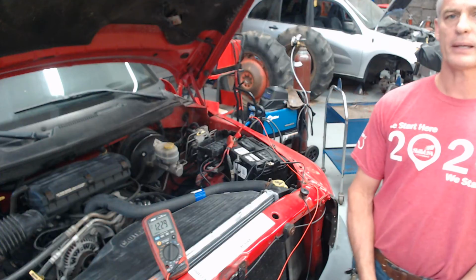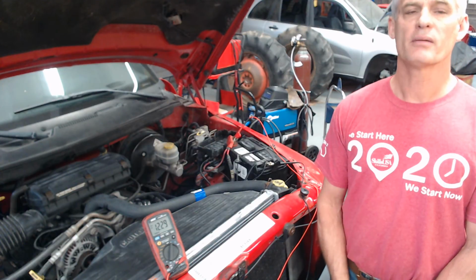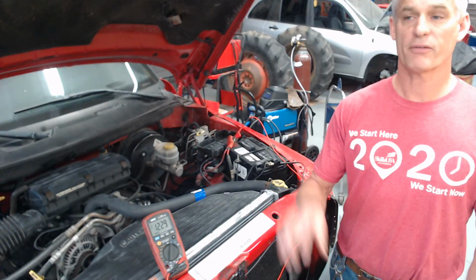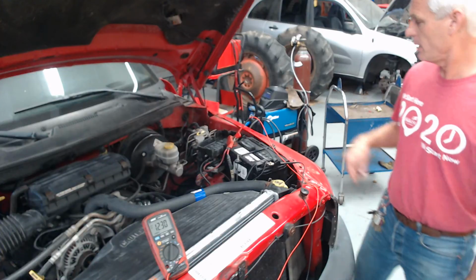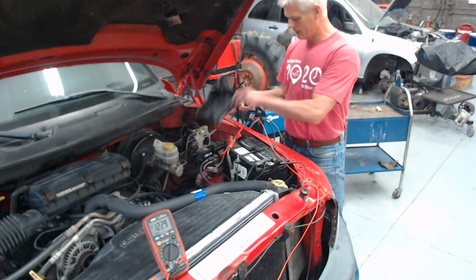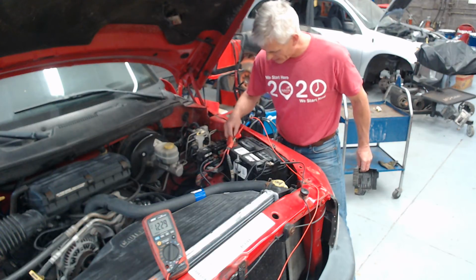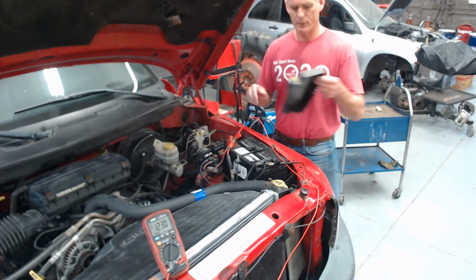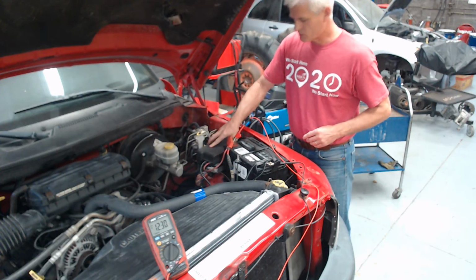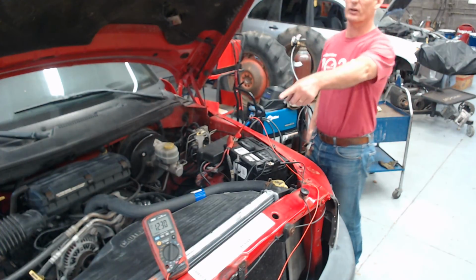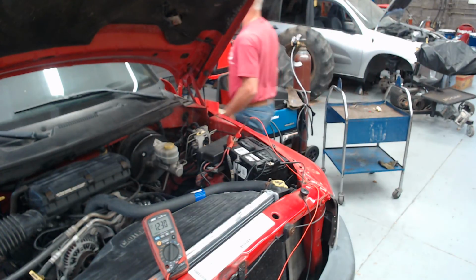And again, by going to ProDemand, go to Engine Performance, Wiring Diagram, find the fuel pump or the fuel pump relay, and you can find the fuse or just pull the relay out. I'm going to go ahead and put that fuel pump relay right back in, and I'll put this cover back on, and we'll start it up and make sure it starts. And you're going to see that voltage go from resting to cranking to charging system voltage. Here we go.